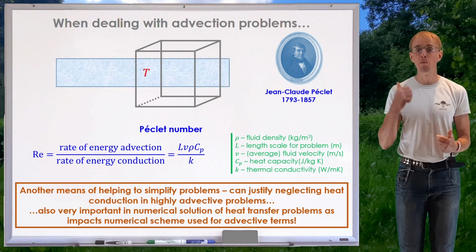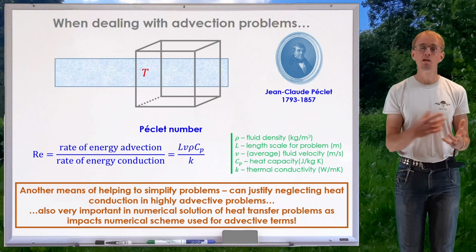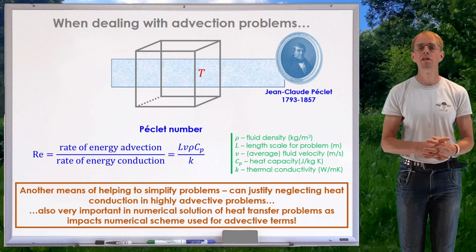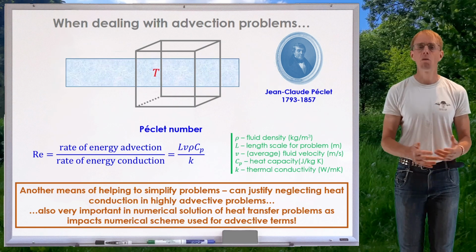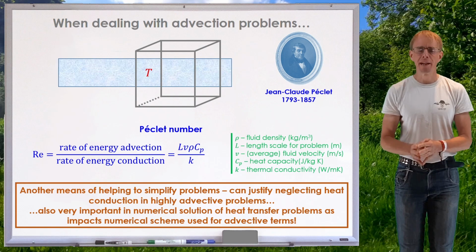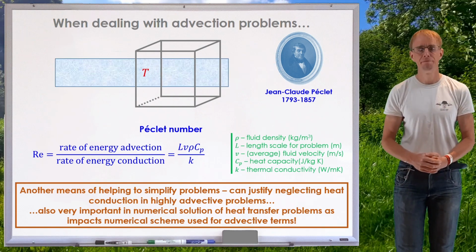And in this case, our dominant information flow is going with the flow. If we include diffusion terms as being equally significant, and we can think of thermal conductivity as a diffusion term, then you actually get quite bad numerical instability. So we're not going to be talking about that directly in the course, but that's another use that we can put the Peclet number to.